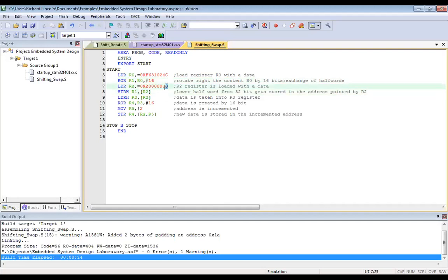So which means this address remains the same. If I have to look at the result, then I have to go into this address and see what the contents of that are. You will find that the value of R1 and R2 will be the same, because it's like copy-pasting the value. Next, when we load the values, I am now moving R2's value to R3. At this point, I have R1, R2, and R3 all the same, right?